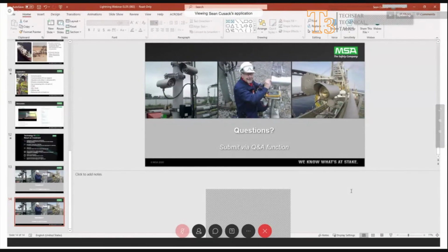It seems the simulated gas check can replace a gas check or calibration. Does MSA find the simulated gas check useful for HF applications? Well, that's exactly what it's for. I have seen a video where someone is filling up a gas check cell in a laboratory, of course. I don't recommend it, but that's the entire point of the simulated gas check function. I don't think anybody would want to put HF in a gassing cell. I've seen it done, but I don't recommend it.